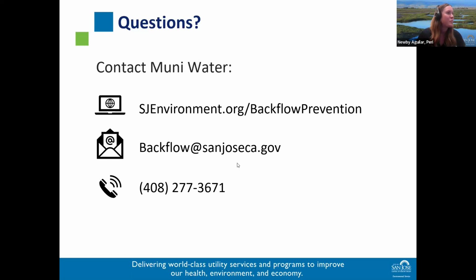What are the requirements for annual testing? I saw from your website that you put it on the homeowner's responsibility. Annual testing is only for our backflow prevention assemblies that are operating on the containment program. Those assemblies are installed right at the meter. Like I said, those are typically our large high-hazard sites, like institutional, commercial, or industrial sites. They have high hazards in the area that could potentially be connected to the water supply, where we want to have a backflow prevention assembly installed.